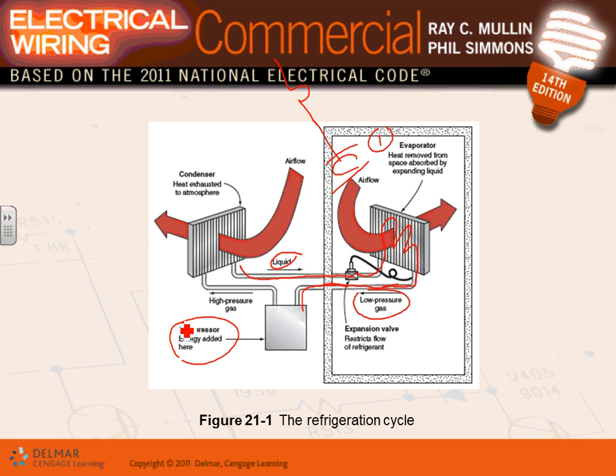The job of the compressor, guys, number two, is two things. Number one, pull the refrigerant from the evaporator. And number two, compress that refrigerant gas from a low pressure gas into high pressure gas. So two functions: pull that gas from the evaporator, as well as compress it into a high pressure. So now it goes in here, we compress it, it comes here as a high pressure gas. Still have a lot of heat in it, guys. So that's the compressor, compress and pull the refrigerant.